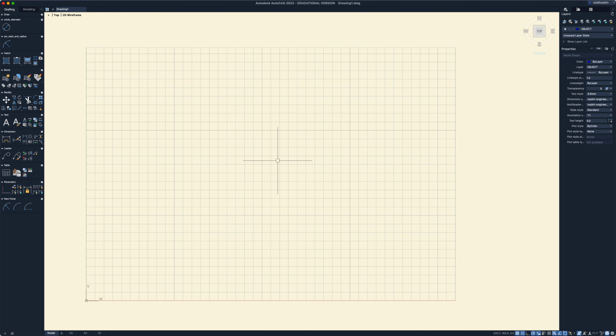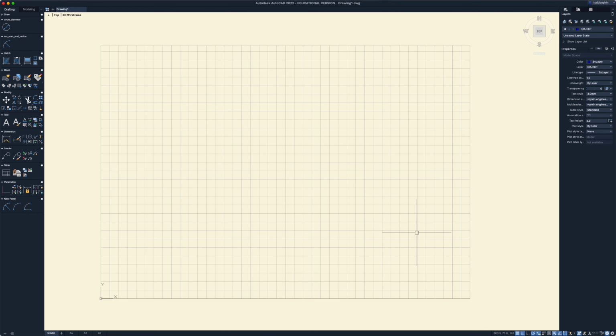This is my engineering drawing template, and I'm going to start off by making a swing door with an opening of 610 millimeters. So notice I'm on the object layer, and I'm going to create the door jamb, or the frame, the left side, which would be a rectangle, REC. And I'm going to make that rectangle with a width of 50 millimeters, and press comma, and it's going to have a thickness or a depth on that frame of 100 millimeters.